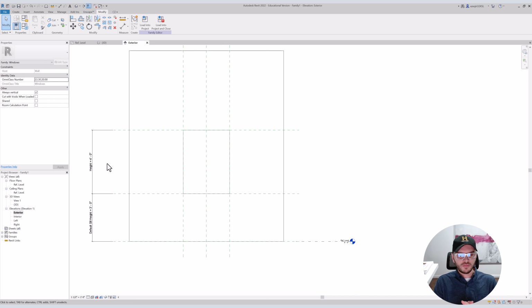So you can add dimensional parameters to all your families that stretch and shrink them, like smaller doors, larger doors. If you have a window with a vertical mullion straight in the center, and you get a window that's longer than 6 feet, you can even have a family that knows to add another mullion after it passes 6 feet, and then recenters both mullions across whatever that new dimension is.